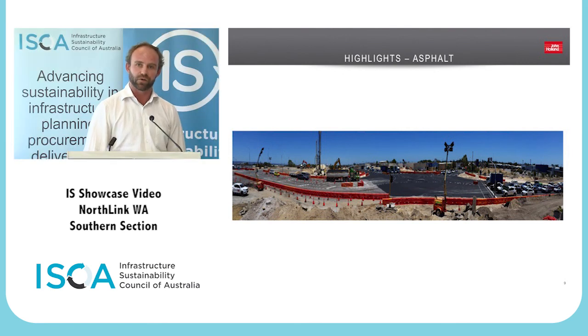We're going to do it in a pilot along about a 700 metre stretch of the road, and it will reduce the thickness by a further 15% or thereabouts, and that will enable Main Roads to demonstrate its effectiveness in due course and hopefully apply it on future projects, which is a significant improvement considering how much of the overall impacts are generated by the asphalt.